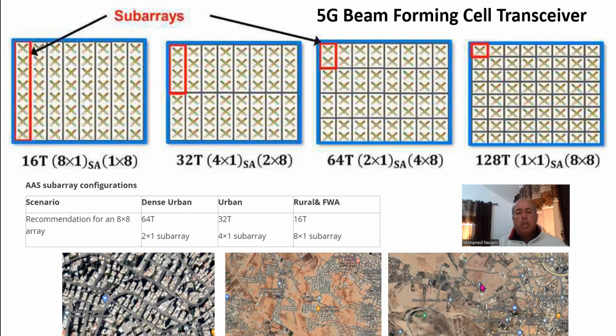For these different areas, you really can't use the same antenna beamforming network throughout all of them. In rural areas, you can have a base station that will shoot the beams to specific areas where there is a demand for data. The users are sporadically displaced, so you don't have a lot of capacity demand, but you have a lot of coverage, because you have a house in here and then 10 miles away all empty until the next house.